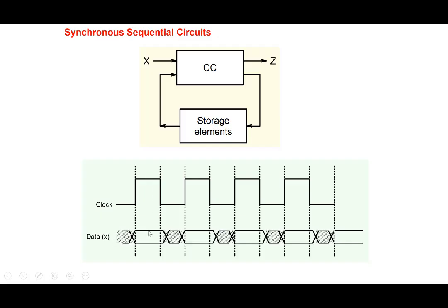And so all data are stable, and therefore the outputs of the gates and everything else would be stable when it is evaluated in this particular time period here. And everything is evaluated here. While in this other case here, you note that data is changing, and the data would be changing with different delay values. So in this period, the outputs of gates may undergo more than one change, it can change more than once.